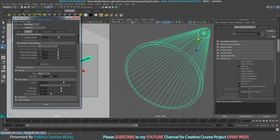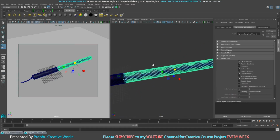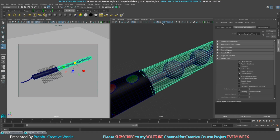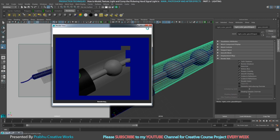So you want to increase the maximum trace depth to the sum of these 2 values. So you want to sum these 2 values. That means 10. If you have some more objects in your scene, you want to increase the reflection and transmission amount. So I re-isolate this one and then click render again. So I will select this view and click render again.